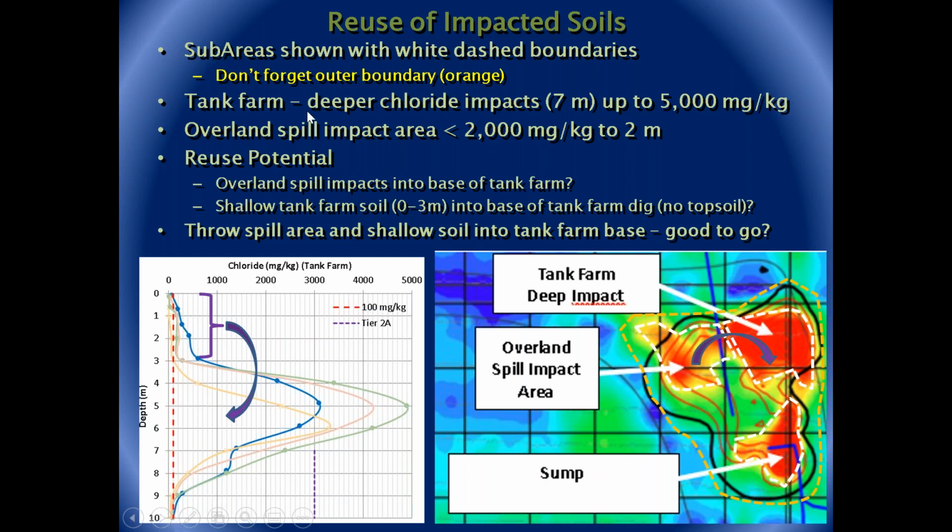So we want to try and reuse low impact material as backfill if we can, because one, it saves on trucking, it saves digging another pit somewhere else to create the backfill source, and perhaps the landowner doesn't need another dugout, or there's no easily or readily available backfill material. It's better for the environment. There's fewer greenhouse gas emissions being released. So there's some real advantages to studying and understanding how you can move materials within your existing excavations.